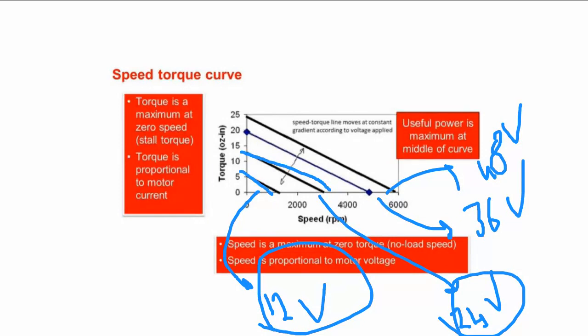That is the fastest that the motor will run, assuming that it's not driving any load. Now there is internal drag, and this is one of the characteristics of brush motors. There is brush drag, and there is friction of the bearings and all the things that go into the internal torques. But this is talking about the shaft torque, that says if there is no externally applied torque, I am going to have a maximum speed.